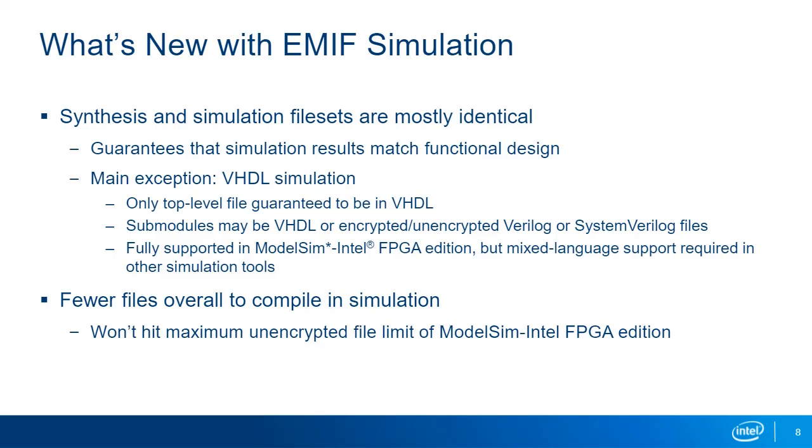If you are familiar with simulating memory interfaces in previous device families, the first thing to note when comparing the simulation process between the old Unify IP and Altera EMIF FM in Intel Agilex devices is that with the new IP, the synthesis and simulation file sets are mostly identical. Besides making it easier to manage the files, using the same files for both synthesis and simulation can help guarantee that simulation results will match the real-world operation of the synthesized design.